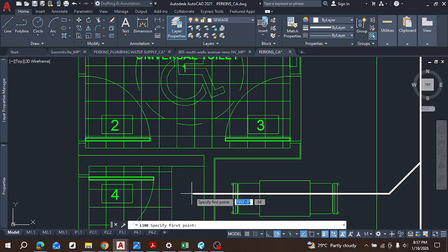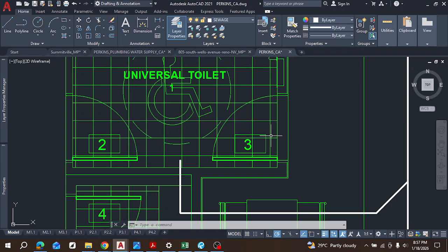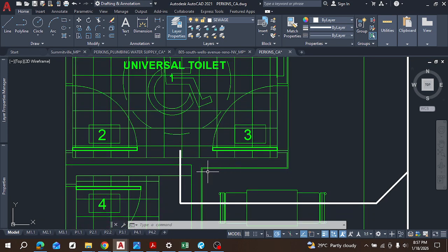Now a floor drain here is not set in stone, it's not very compulsory, but just to make your system standard, you can add a floor drain here so it flows out through here. I didn't want to give it its own pipe because I'm trying to make economic use of materials, and it's close by.